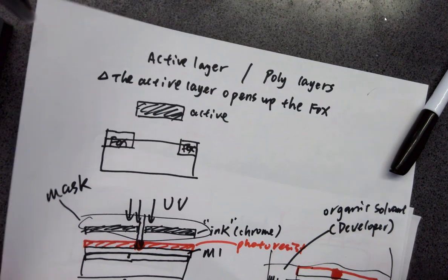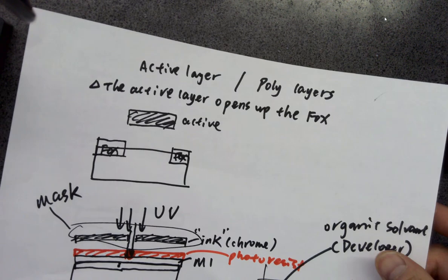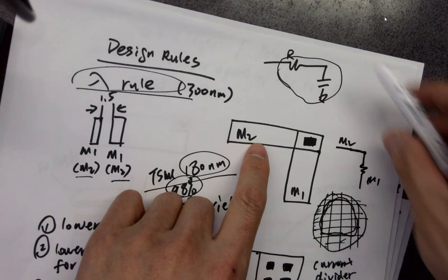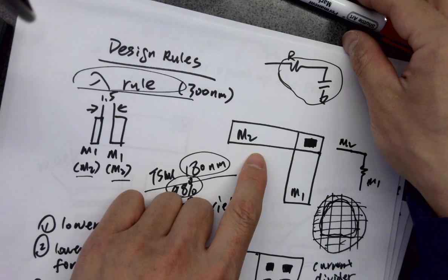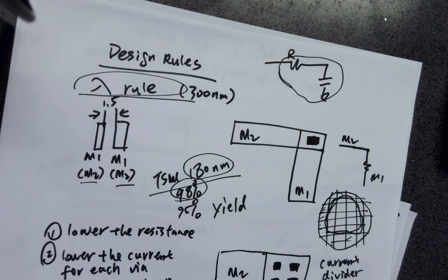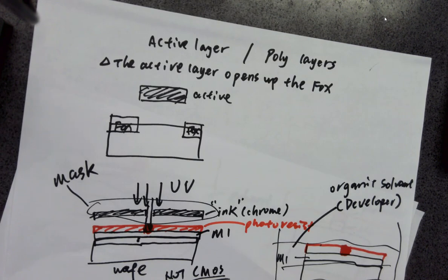So this is just a very simple example. You can imagine you have a large-scale circuit. All these layers will be printed into masks and eventually fabricated on the wafer in different layers. They fabricate a layer and deposit silicon dioxide for that layer to insulate it, and then go up, fabricate another metal layer, and deposit another silicon dioxide on the top to insulate it. It just keeps going up, so it's called a bottom-up manufacture procedure. Eventually you can get all the layers done.